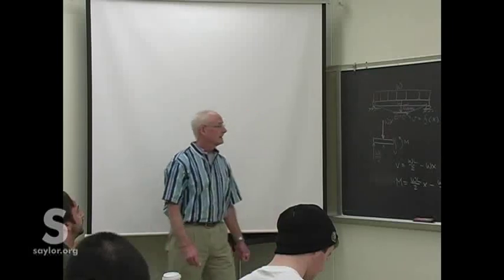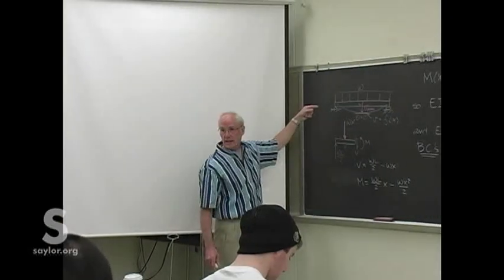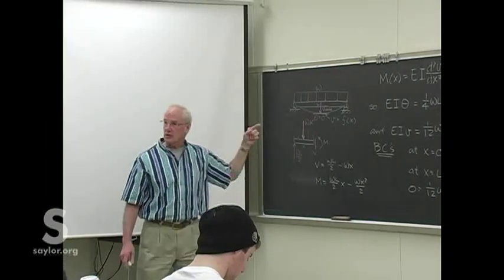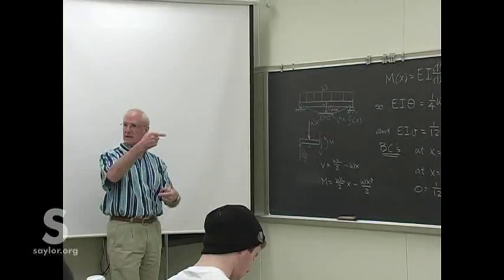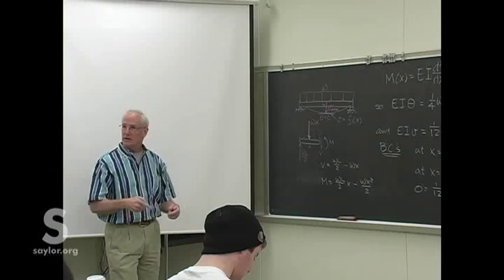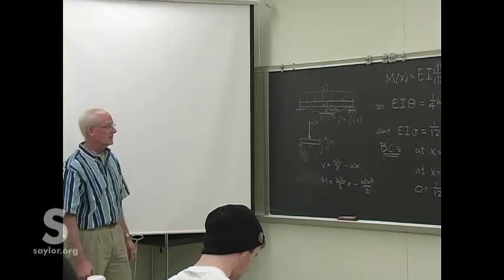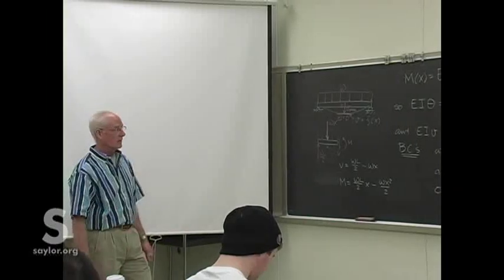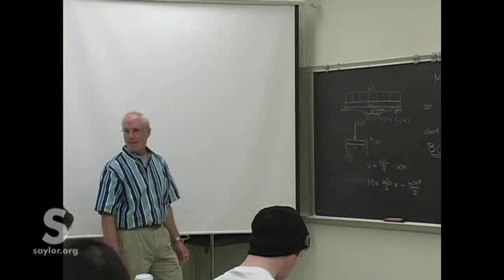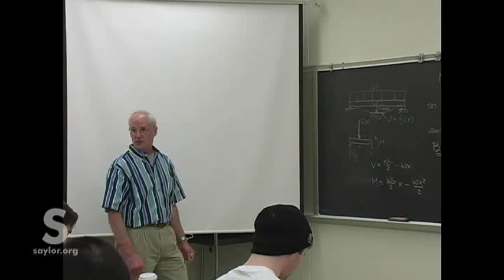Splines, yeah. One of the characteristics of the elastic curve is it never has a discontinuity in the curve itself, because that means the beam is split, nor in the slope function, because that would mean a sharp bend somewhere in the beam, and the beam has failed at that point. These beams don't fold very well. They tend to break before they fold. And effectively what they did during the olden days was to form beams to create a line, right? To draw a nice curve?